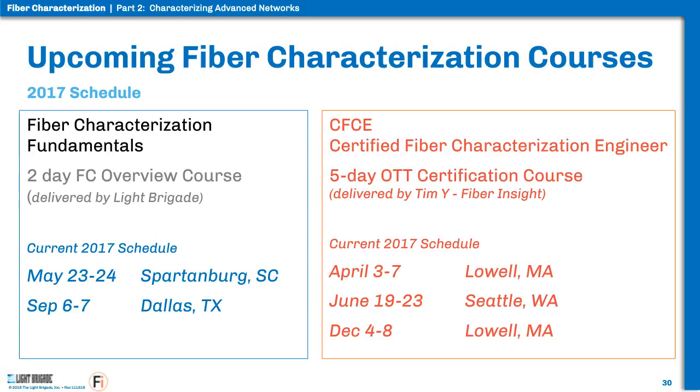PDL is polarization-dependent loss, and generally you only worry about PDL when you're dealing with optical components. When I used to work for Agilent Technologies, we had a PDL tester that would actually measure the polarization-dependent loss, which is a loss contributor. It's an attenuation contributor based on the polarization itself. So I would say it's not a major contributor. You could have polarization-dependent loss, but it's more going to affect the attenuation, not the polarization mode dispersion.